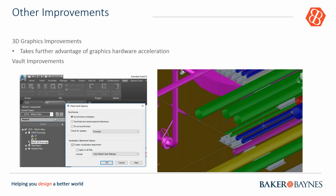You found that there was also multi-select of lines during the production of quick ISOs, okay? Also export to PCF files, okay? That's also possible in 2019. And also the valve operator improvements, okay? So there's some improvements made there as well with the inline assets, with changing the valve operators, and also reducing T-size annotation with 3 ports. So this is a really, really nice improvement that you found.